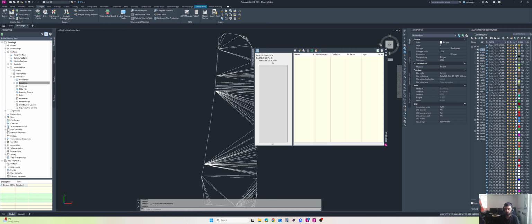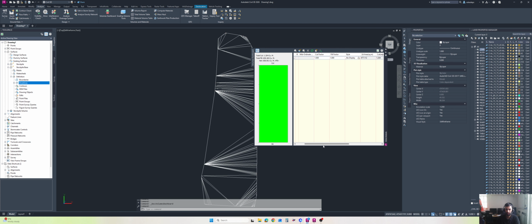It's creating the surface, as you can see in the bottom right corner of Civil 3D. As I mentioned, the stockpile is very dense, and the surface was very heavy, and you can see this is the stockpile volume we have here. It is all in green, so this is all the fill volume, like 659 is our stockpile volume.